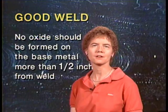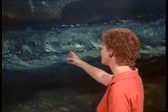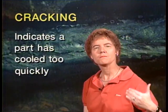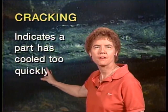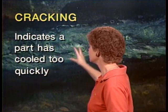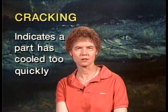Now, let's assume you've got a weld with a crack. If you've got cracking like this, that's obviously not a good weld. And what it means is that the part has cooled too quickly after being welded. That cracking comes because the part has cooled too quickly after being welded.